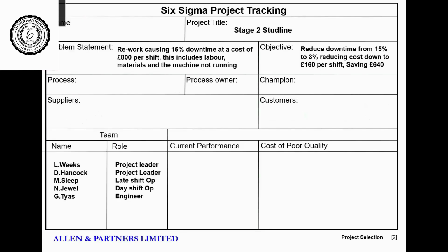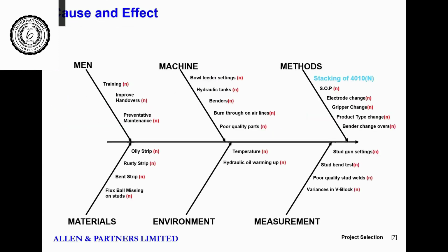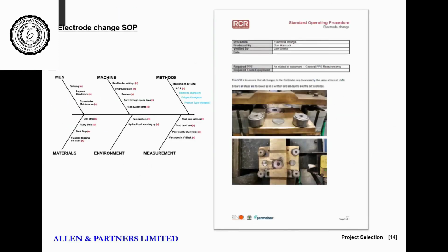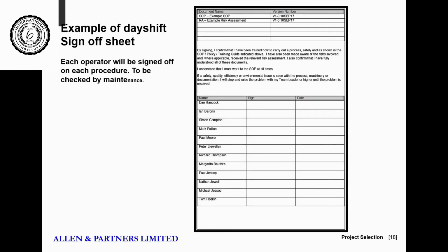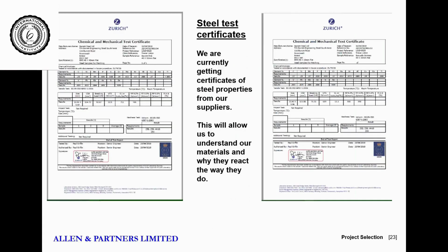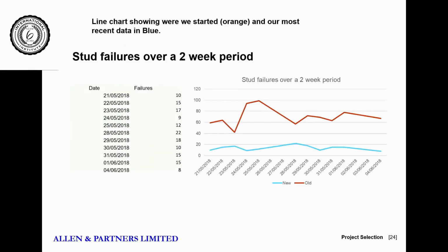Just a reminder, this is the welding process. We had rework. What did they do? Process flow, cause and effect. They put some controls in place, wrote some standard operating procedures, turned many of those variables that weren't controlled into controlled variables, and transformed the performance of their process. There's the transformation. Now again, this is a lower the better graph. Still process capability though. They've just driven that result down and they've made the result behave itself. That's what process control is about. Taking variability out of your inputs.